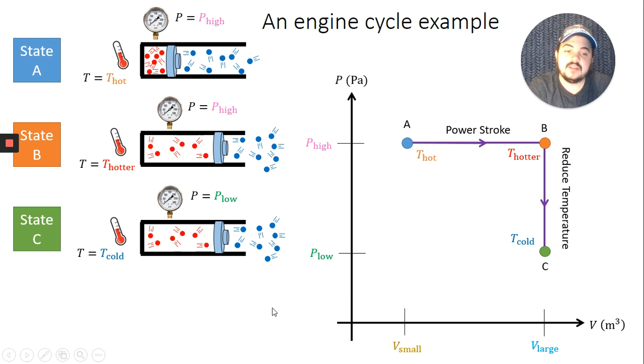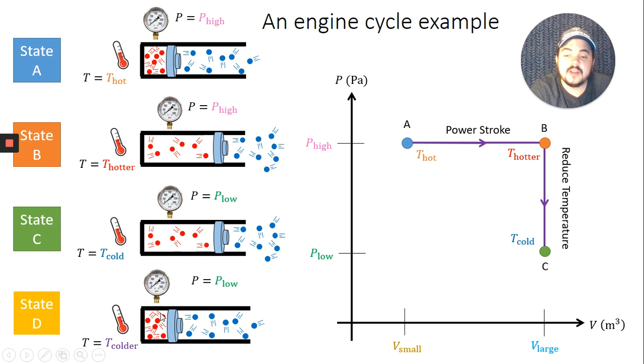So now we've reduced the temperature. Sorry, I forgot to say that. We're now at state D. We're going to compress this gas back to where it was. We're still at our low pressure at state D, so we're somewhere around here at this coldest temperature. In order to maintain that same low pressure, we're going to need to continue to remove energy through a cooling process as we go here. We'll connect C to D, connect them with a line, orient that with an arrow.